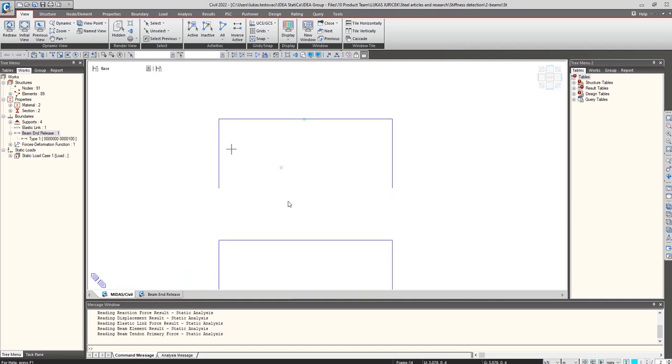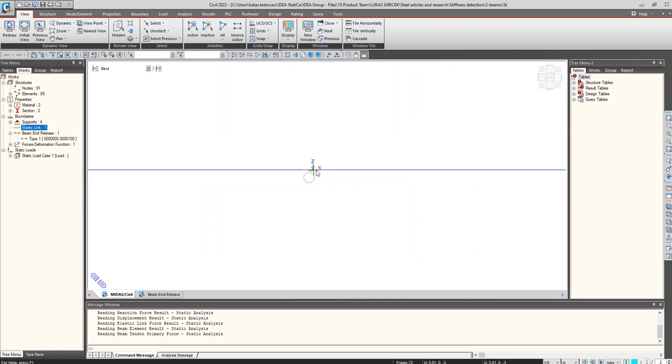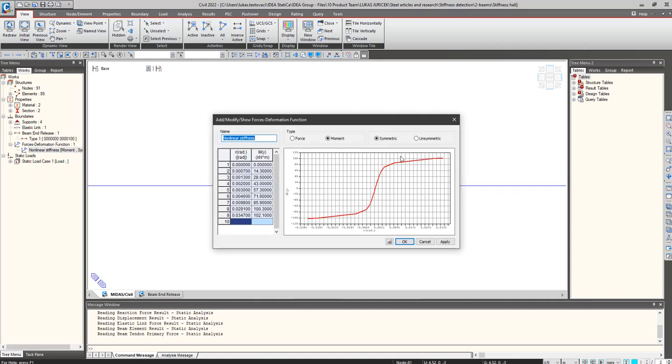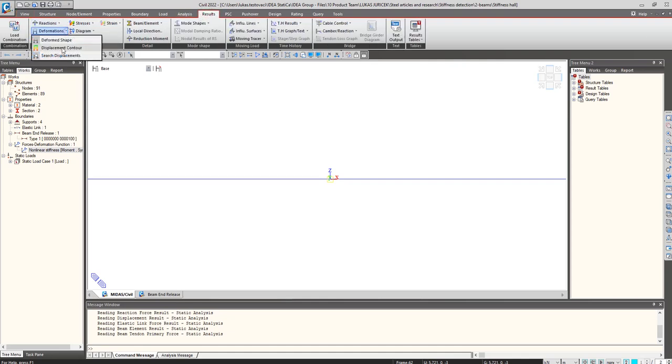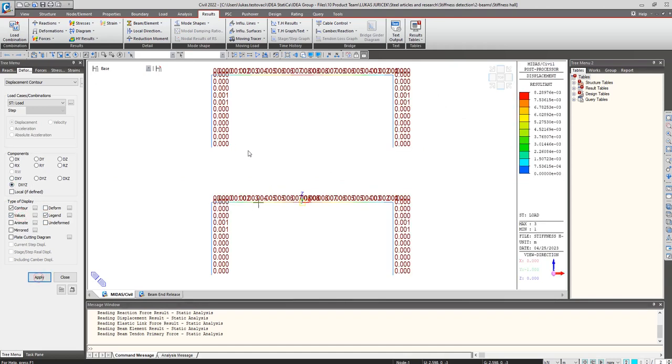The second function, which is related here, is in the part of the elastic link where I'm connecting two nodes, and my function is completely non-linear. This is the trend which is symmetrical on both sides, and these numbers are taken from the CSV spreadsheet. So let's run the analysis to see the results. I will run it. I'm getting the results, and in the results we can see at first the deformation. So I would like to see the total deformation and check the results.